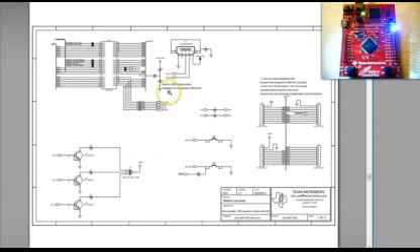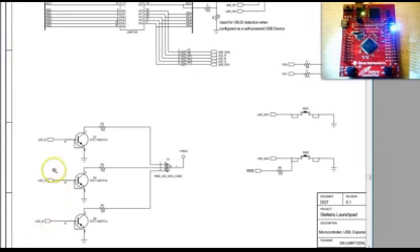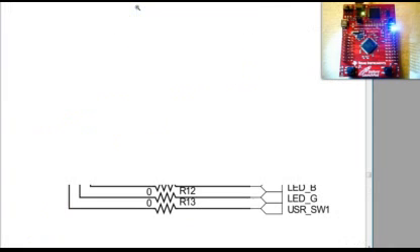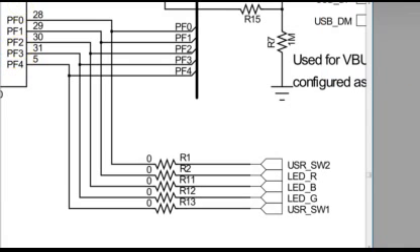On the first page of the schematics, you can see that the R, G and B components of the user LED are powered by transistors, which are controlled by outputs LED R, LED G and LED B respectively. You can see these outputs again higher up in the schematics, where they connect to the microcontroller pins labeled pin F1, pin F2 and pin F3. The letter F in this case stands for GPIO-F.